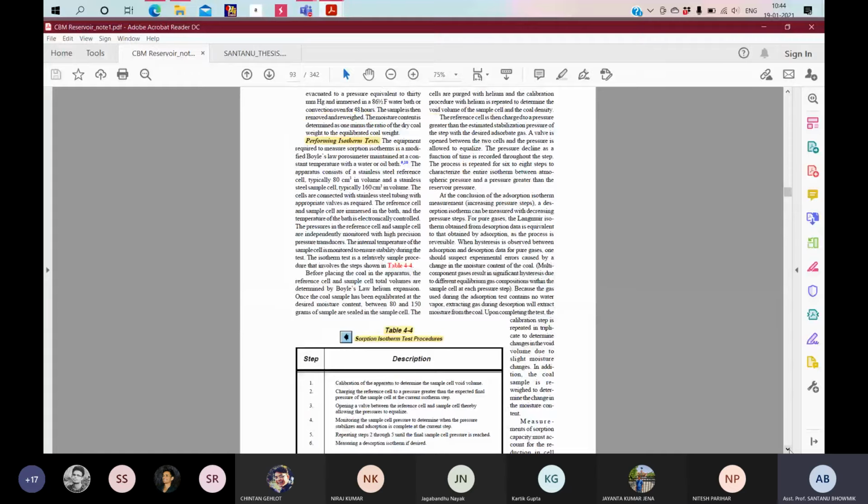What we are going to see here is that the pressure varies, the temperature is constant. We are going to take some 6 or 7 steps of pressure at uniform gaps. That means suppose you are going to do testing from 0 to 7 megapascal, at each 1 megapascal, so the pressure steps will be first 1 megapascal, then 2 megapascal, then 3, and so on.